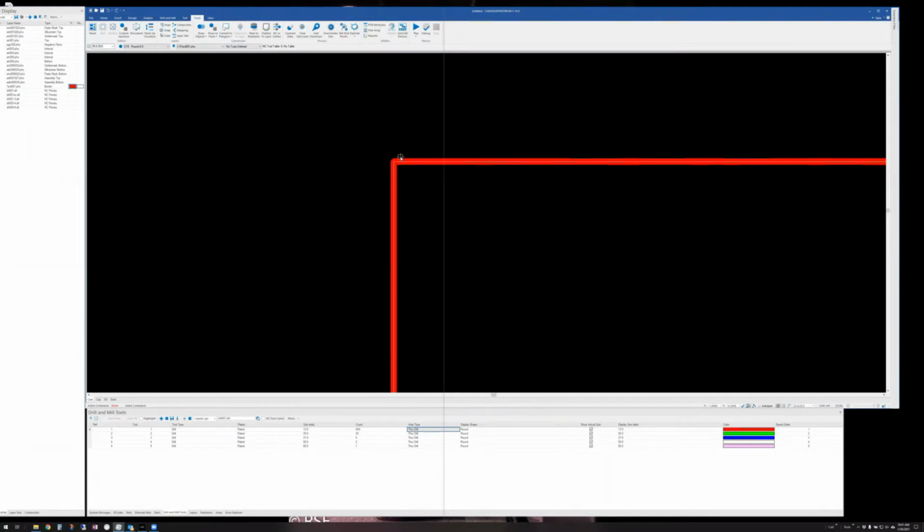And I mentioned this early, that we'll use that now if we do copper to board edge checks. We'll use that for panelization, whether we use the fast array module or the panel editor, to properly space the boards between each other.